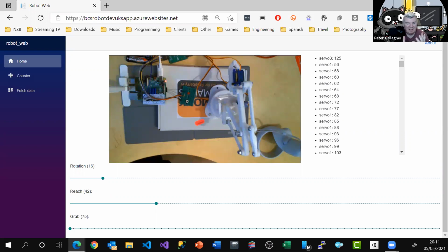If you've got an ESP32 sitting in the middle of the savannah in India or Africa or whatever, then you can't really get that data out by telling somebody to go and get it off the SD card. So the ESP32 has got a GSM module on it. It's a really basic 2G modem, essentially, that you have to fire AT commands at. But I created an Azure function that this can control. The ESP32 over GSM connects to the Azure function, and then that hooked itself up to IoT Central. I quite like IoT Central, a software as a service offering from Microsoft that lets you ingest IoT data and then stick graphs on the screen and control devices and stuff.